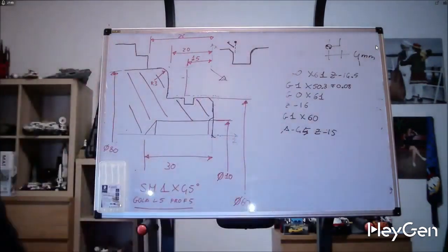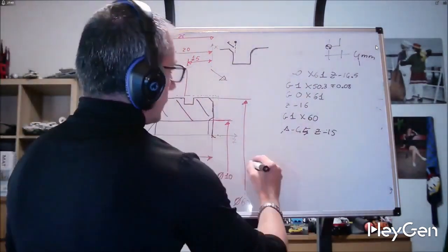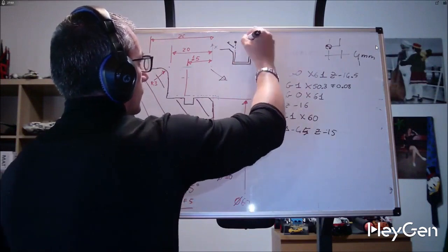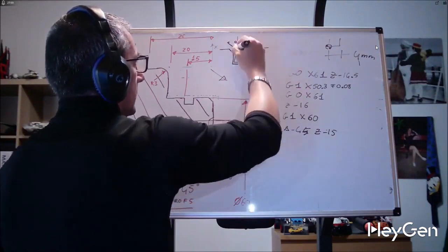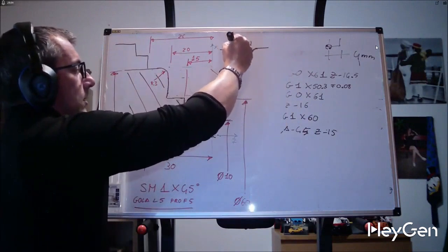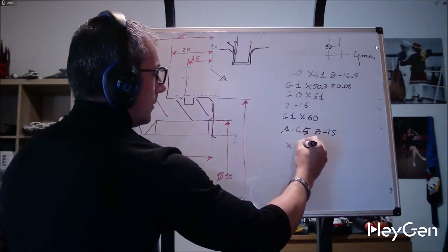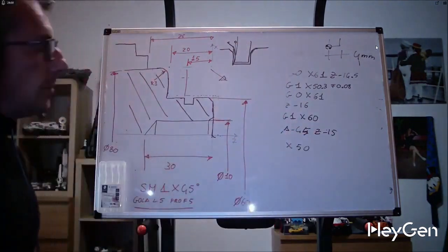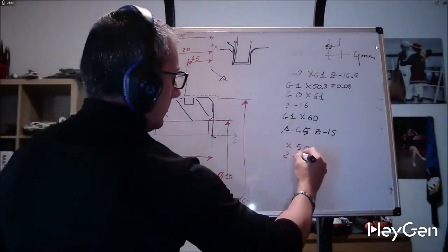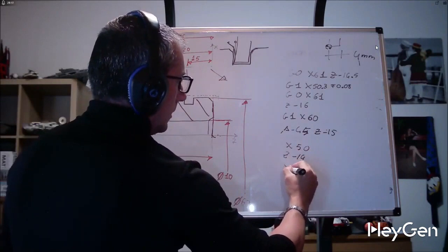How much do I move to make a groove 5 wide with a 4 tool already roughing the groove? Because we have already discussed this with the first implant. I am here at 45 Z15. I go to the bottom. So G1 X50. Obviously, I will just need to widen by 1 millimeter. So Z14 and return to X60. And return to X.